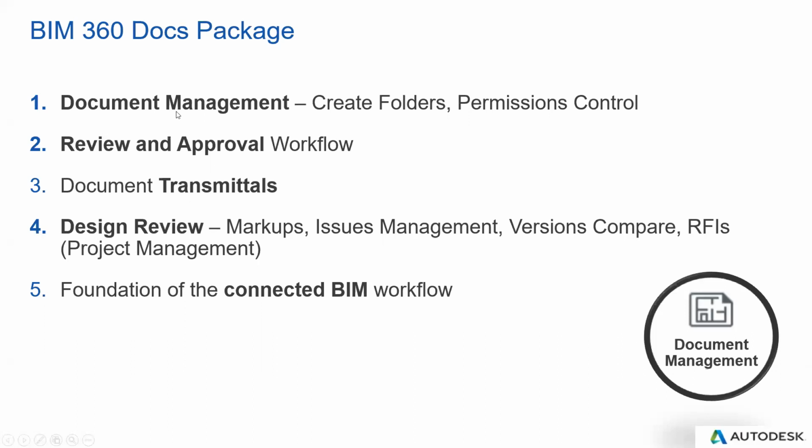Also, when we have put all the documents or drawings and information inside our BIM 360 Docs, the document management module, we can start to review our information, such as do some markups. Markups is just you write something here to point out the problems, and everyone can see the problems. However, it is not ideal because you just mark up the problems, but you haven't assigned who should answer your question and no deadline.